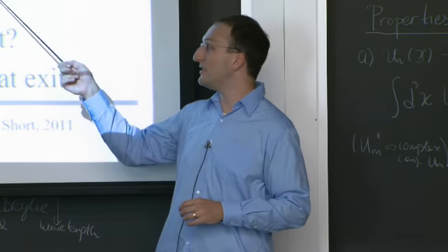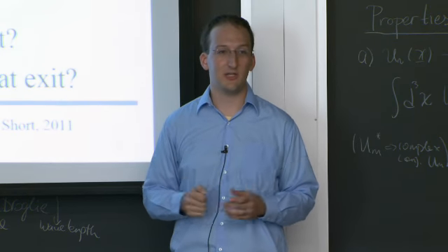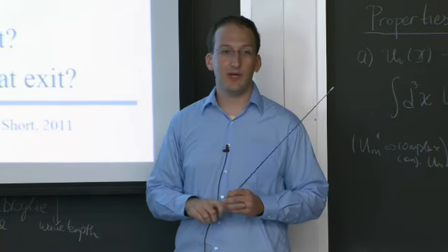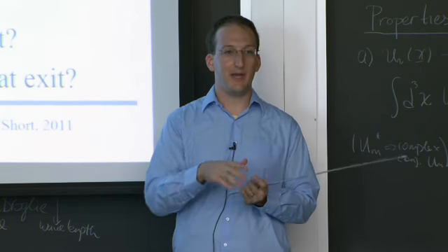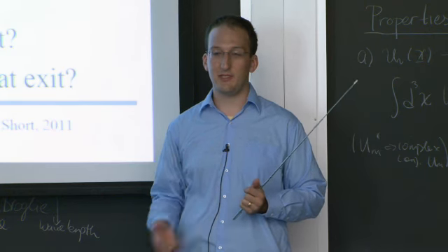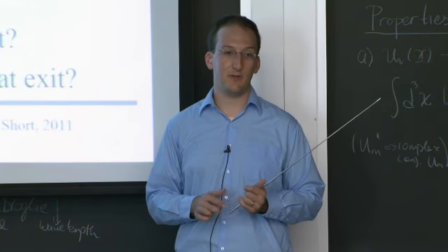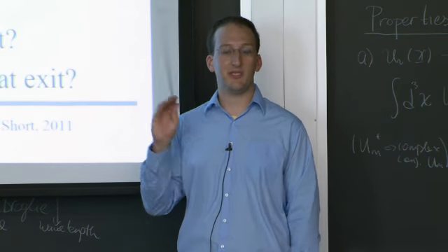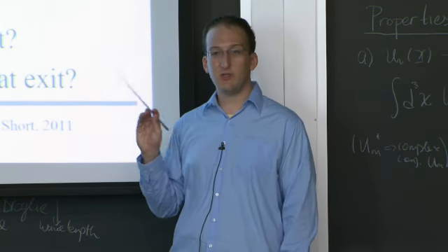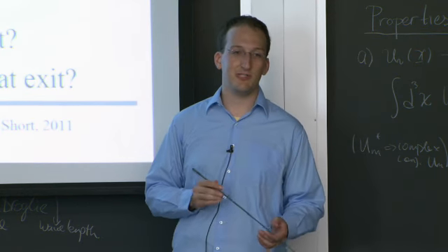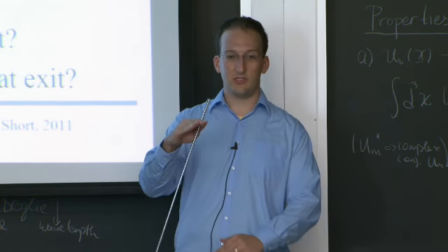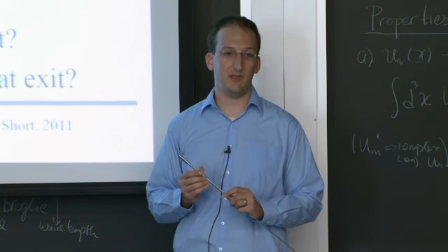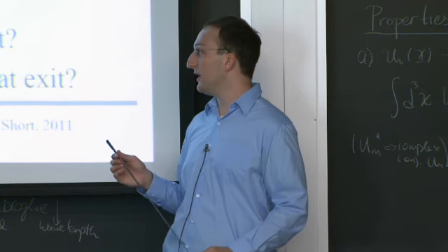Is it going to have primary, secondary, tertiary cycles? What are the heat exchangers going to look like? What are the implications there? Will it have a recuperator, as in will the hot and cold streams pass by each other to help raise the inlet temperature, for example? So let's say you had a very high temperature reactor with an outlet temperature of 1,000 degrees. You don't necessarily want to bring back in 100 C gas, because having a huge temperature gradient can have some pretty bad thermal expansion stress effects. Lots of other bad things could happen.